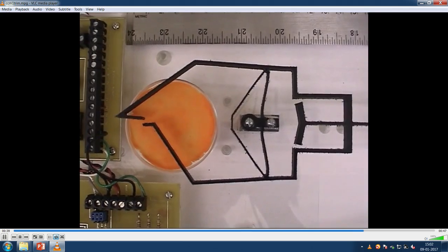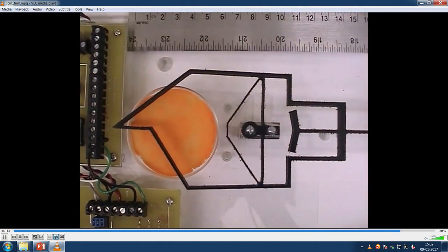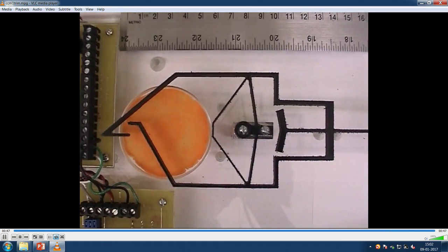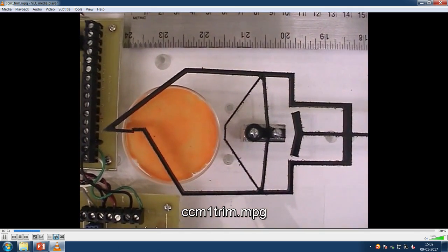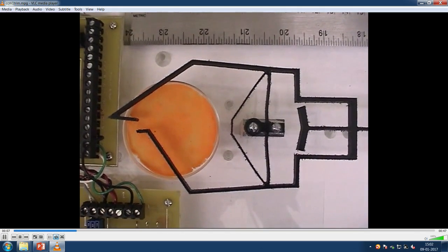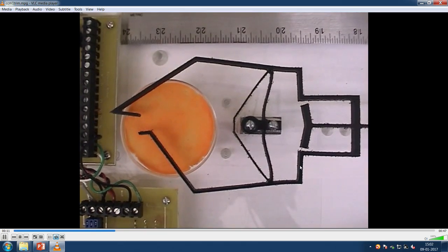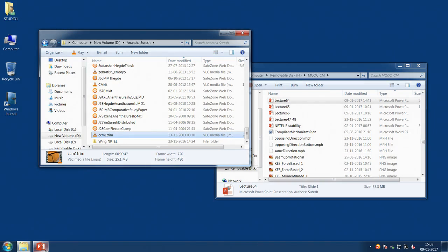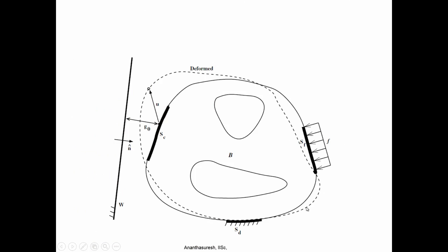Okay. So, this is how you can get very complicated motion. If you see this black one, which is polypropylene available in black color, it has a single piece structure, that is, there are no joints anywhere. It is just that there is intermittent contact over here and over here. Okay. So, that is the contact aided compliant mechanism. Let us go back to the presentation.